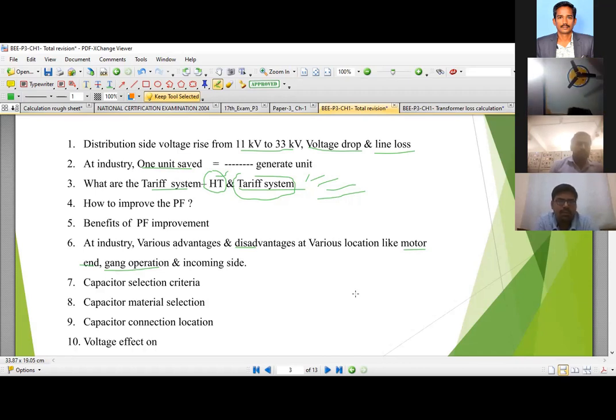Maybe if we can separate by load center, 3 motors from one load center, another 4 from another, and another 3 from another center. But even then, using only one capacitor, it will affect all motors at the same time.